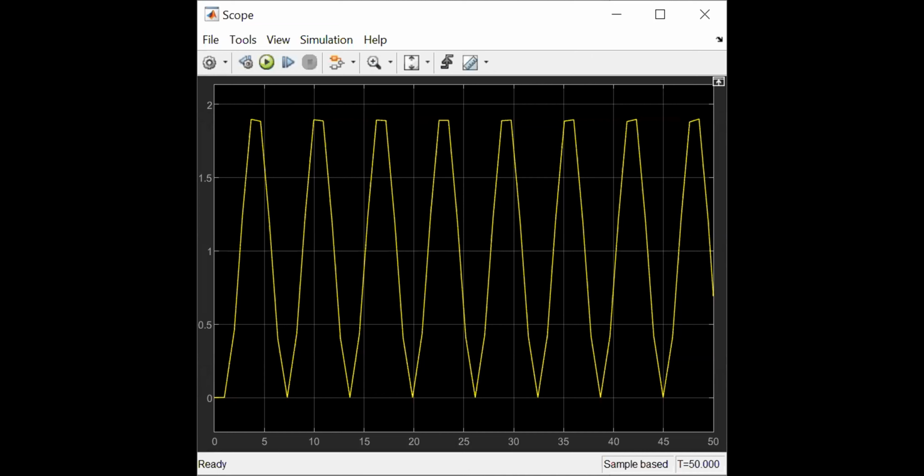So to give you one more thing, just go back to your sinusoid, connect the sinusoid to the transfer function and run. And now you will see that your sinusoid looks pretty nice. So once you change the solver step, you should be able to get smooth output from the scope. The last part that remains is connecting the block to the ramp. I trust that you'll be able to do it on your own.